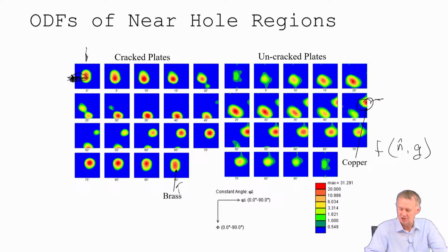It actually also goes along this position. This one here is also showing an alpha, right? It's a symmetrically equivalent position. And then to show the beta fiber, you have to start here with your brass and then come up to this point, just follow this intensity through. These are S textures as you're coming through here, all the way up to where your copper texture is. So brass and copper, or Dillamore component, are the 2 ends of your beta fiber. Yeah.